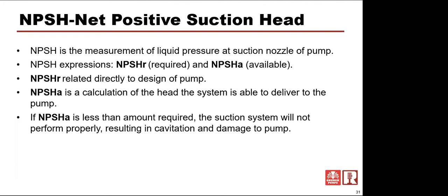And it has to have enough pressure to fill all of those pump vanes as this pump is spinning at 1800 RPM or 3450 RPM or whatever RPM it's spinning at, so that we don't have any voids. We're filling all those pump vanes properly as this thing is spinning.